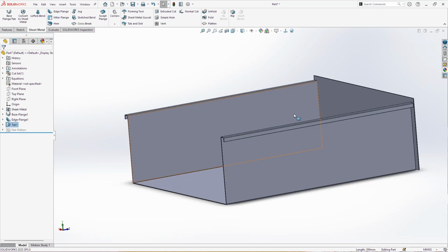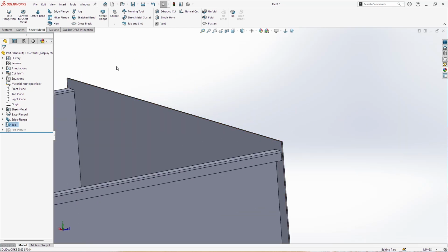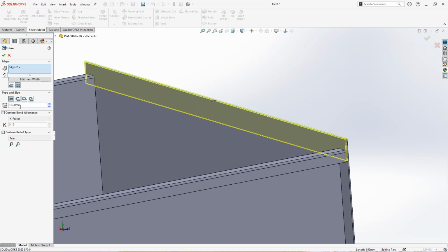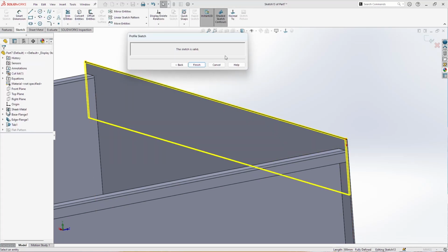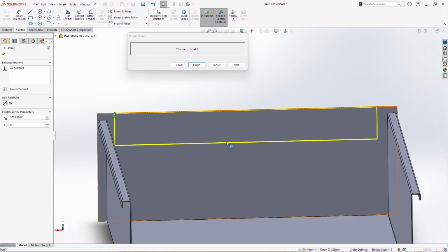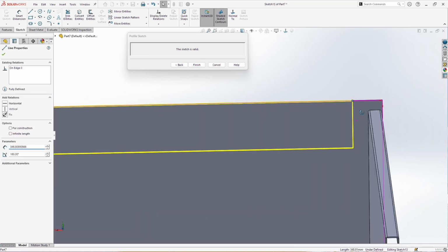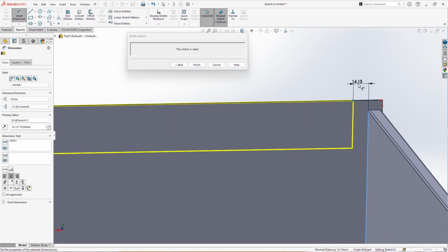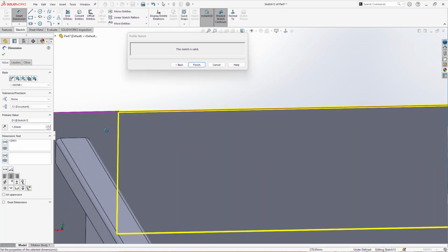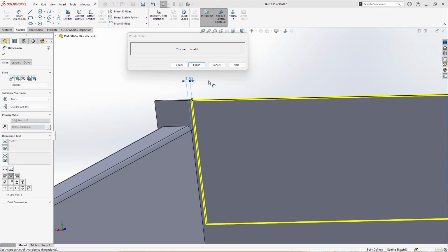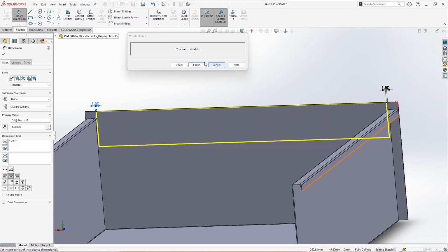Now we need to create one hem. It's going to be here, 45 millimeters. Edit hem. Change these 2 points first. And now add one dimension, 1.5 millimeters. Also from this side, 1.5. Finish.